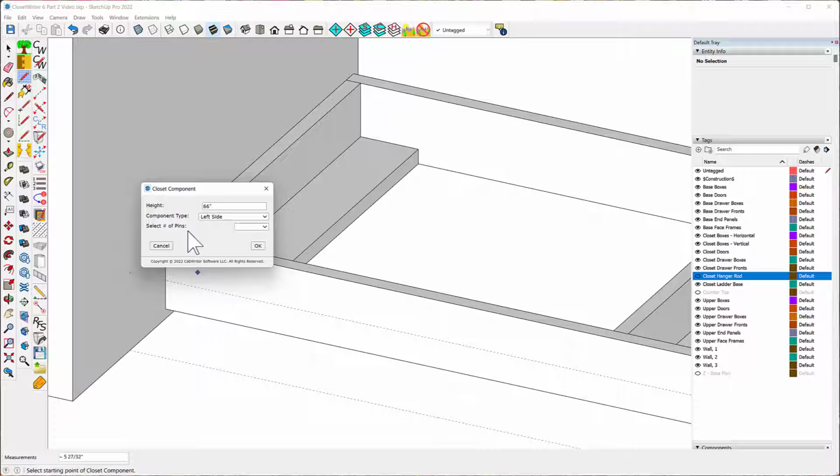All right, so now all of the rest of the dimensions of the side are determined by defaults that I have set up. And as I said before, I chose defaults that are going to work for my particular design: a 24-inch deep cabinet, and a cabinet that has a back, and that back is a planted back, and the material is 3/4 of an inch thick for sides.